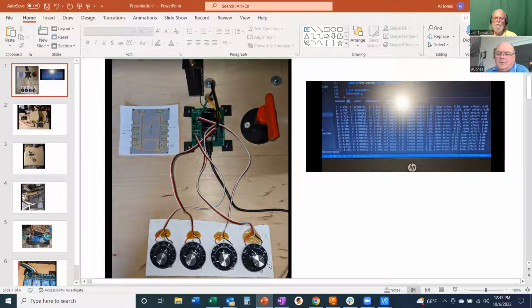Yeah, remember, so yes, I knew that I was averaging the analog pot that is the actual steering value. I wasn't averaging this one because, again, this is just a configuration program, and I'm expecting a steer angle target to come from the ROS navigation stack.